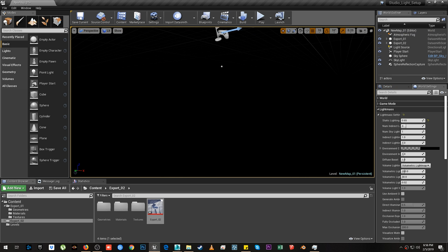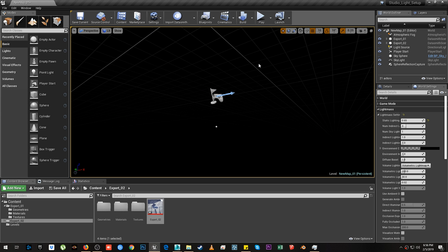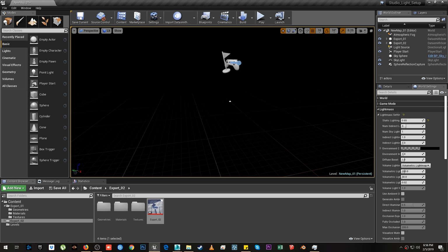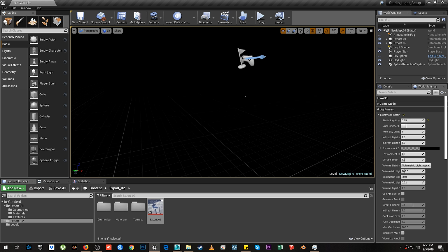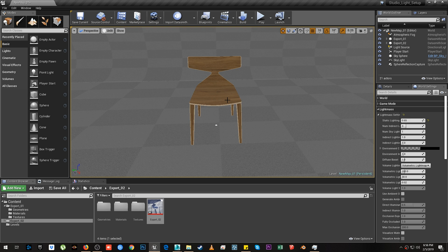So as you can see, once I hide the sky and then fog, then you can see it's absolutely dark, and by this way I am sure that there is absolutely no lighting or no light source present inside the scene. So after that, what I'll do is I'll just go ahead in here and then in perspective, I'm pressing Alt 3 to go inside unlit mode.